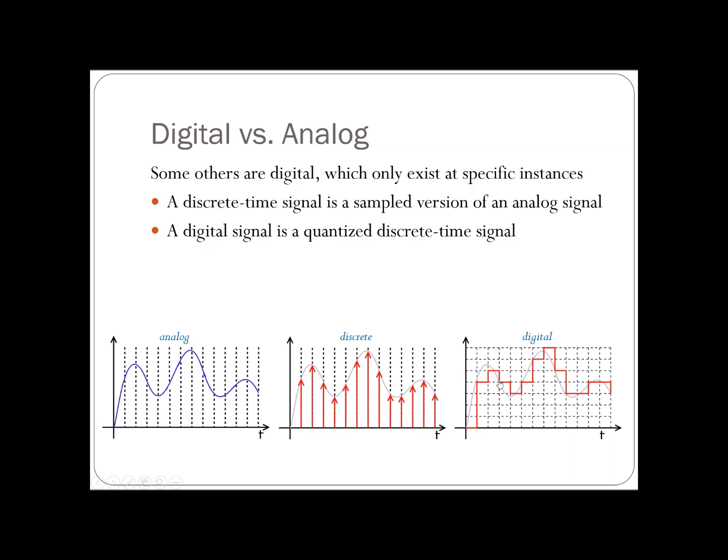So here you will have first a stair-like signal, and then the recorded value might be slightly different from the analog signal due to the discretization of your recorded value. So you have two discretizations: the discretization in time, and the discretization in the value that you want to record. That's how a digital signal is recorded in your device.